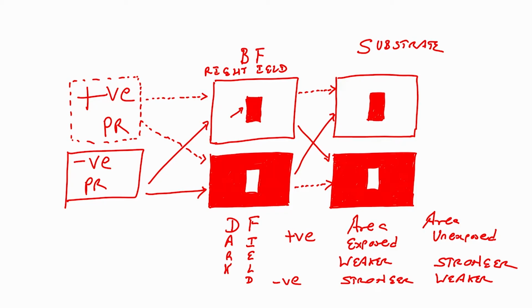That is why we are talking about this, extremely important to understand when you will have to use a bright field mask or dark field mask, how the area which is exposed, what kind of pattern you will get, if the area is not exposed with UV light, what kind of pattern you will get. So, extremely important to understand bright field mask and positive photoresist, dark field mask and positive photoresist, bright field mask and negative photoresist, dark field mask and negative photoresist.